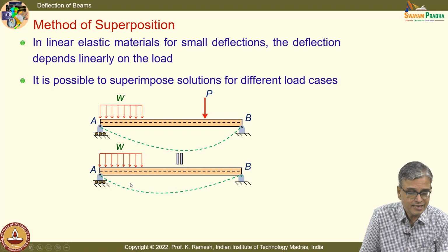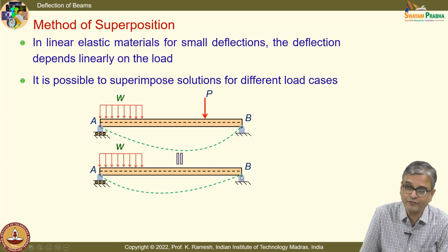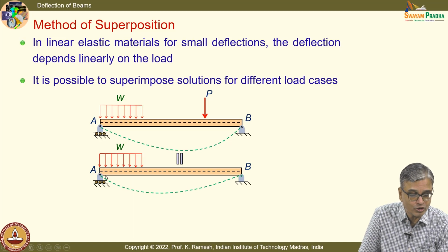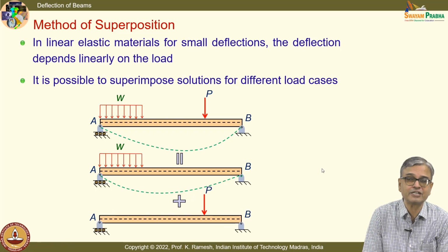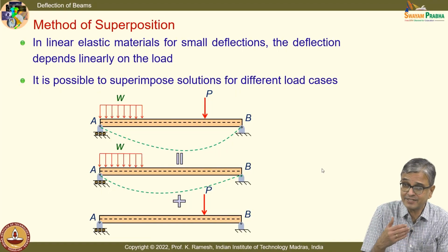So, this will be unsymmetric and it will have 0 deflection. It can have different angles. See, I have shown deliberately the slope is different from the slope here. And when I have the other load, here again you make an attempt to draw the deflected shape, because that is very important training.